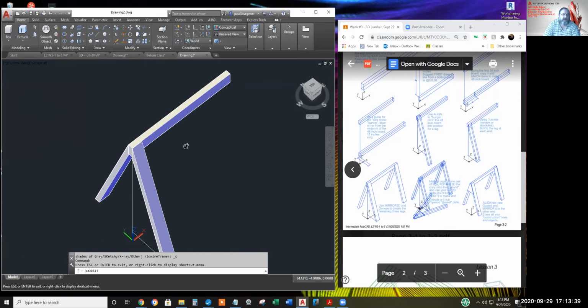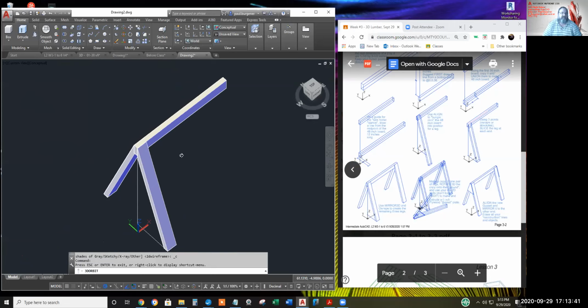I'll admit, I tend to use the 2D mirror command when it works, rather than specifying 3 points for the mirror plane, or as Dan pointed out, ZX enter, specify 1 point.